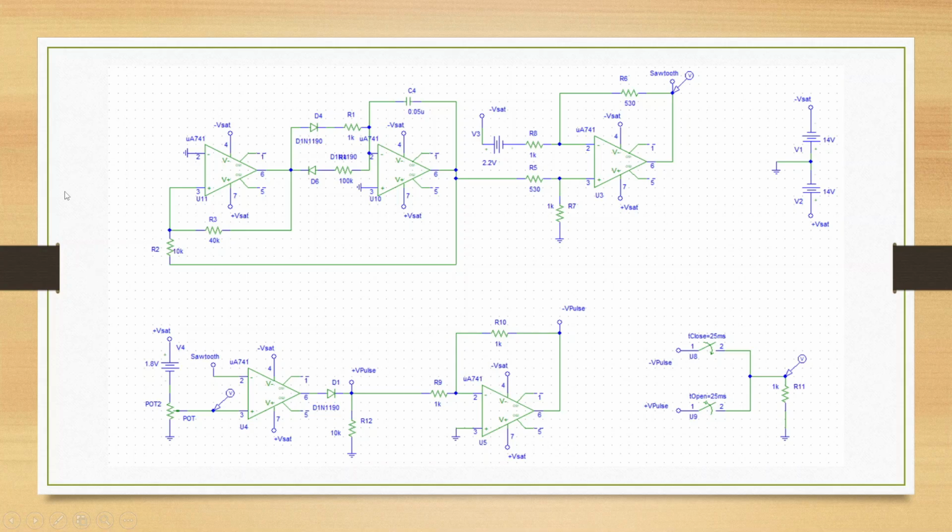Basically, the circuit starts from the left of the page with creating a square pulse which is passed through an integrator circuit to produce a linearly changing voltage. The resulting waveform rises gradually and falls sharply, which is the characteristic of a sawtooth wave. The resistors in the circuit are selected to regulate the current flow during the rise and the fall intervals.